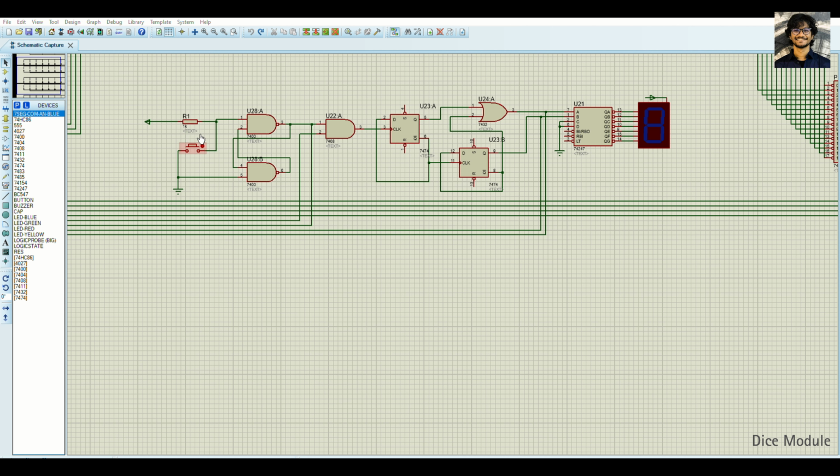But when we use the push switch present here, we make both of our inputs ground, thus giving us the logical 1 in the AND gate. So, whenever the push switch is pressed, the SR latch gives us the value 1, and then the AND gate passes the clock pulse, which is then supplied in the later parts of our module. When the push button is turned off, the circuit gets opened and the AND gate receives 0 and doesn't allow the clock pulse to pass through the later parts of our circuit.